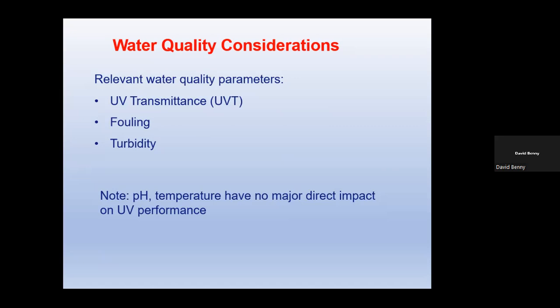When we put the disinfectant into the plant and attempted to run it, the UV system was very compromised in that the fecal coliform level was not affected at all. So even small concentrations of color, anything over 50 Hazen units, compromises the effectiveness of the UV system.